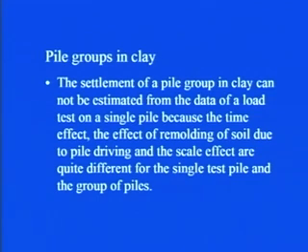As you have seen, we have already discussed how pile tests are conducted in the field. You saw that there were two types of tests, and then we plotted the load settlement curve, and from there we found the ultimate load carrying capacity, and corresponding to that you can find the settlement also. But the test has been conducted only on a single pile, not on a group of piles. So, that data cannot be used confidently in finding the settlement of a pile group in clay.